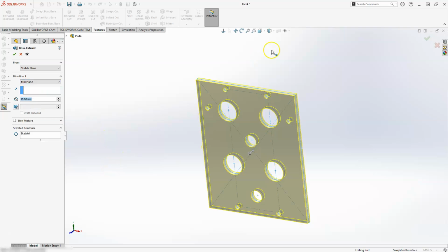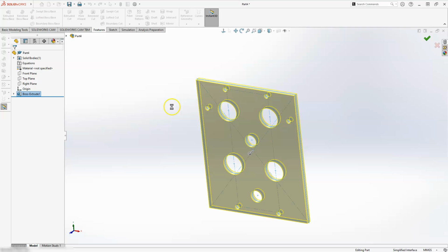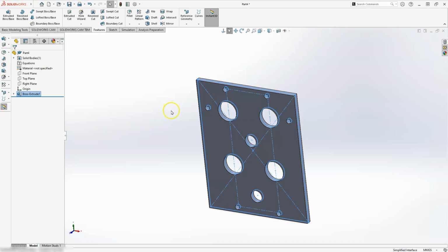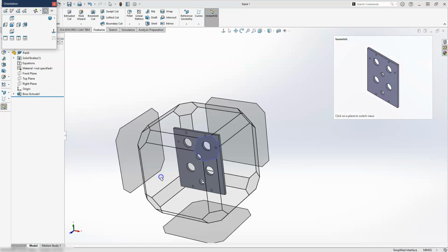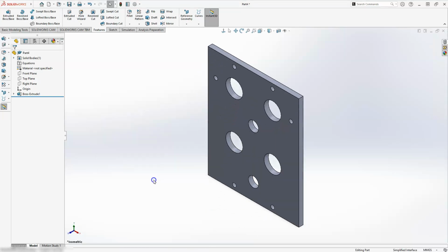And then I'll go ahead and tell it that yes, we're done with it. So I'll go ahead and hit the OK option here. It should create or produce our solid. Once I do one little left click here, the profile of that sketch will go away. I'll go ahead and hit the space bar, and then I'm just going to select here. And that's going to give me my isometric, right?